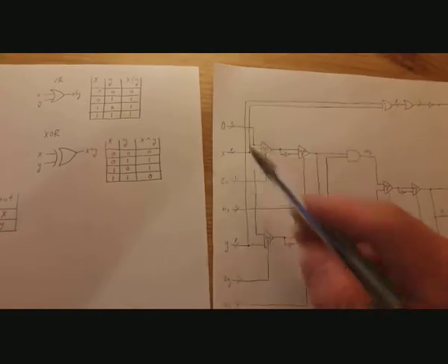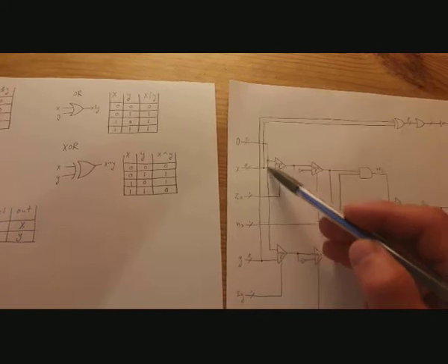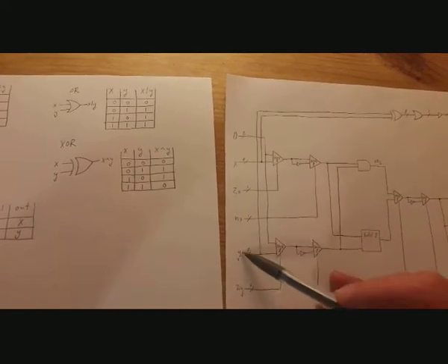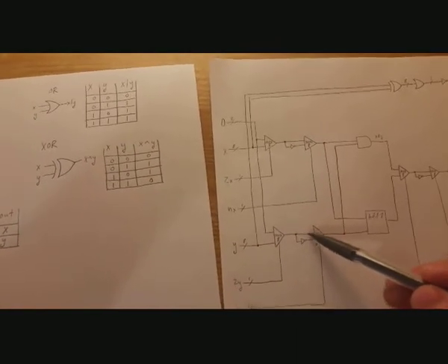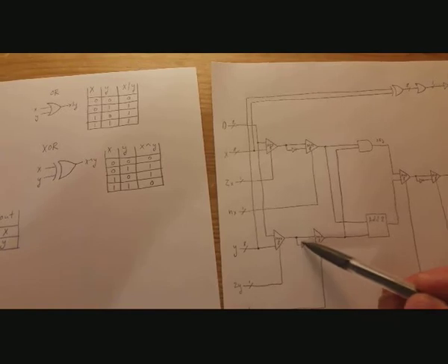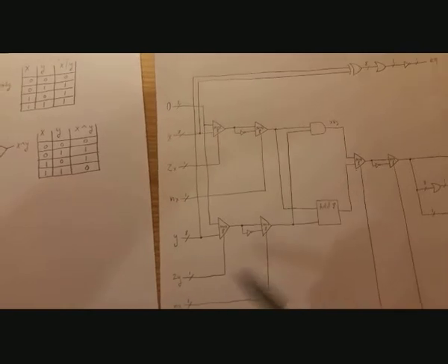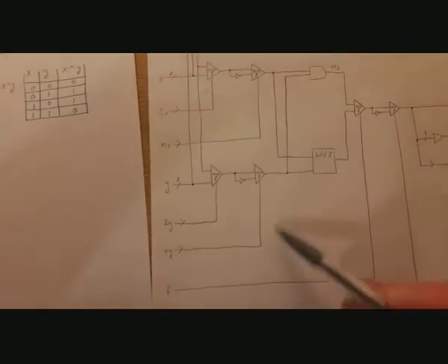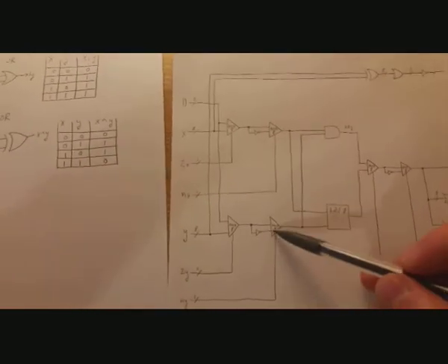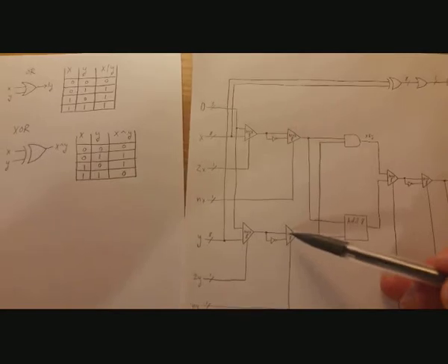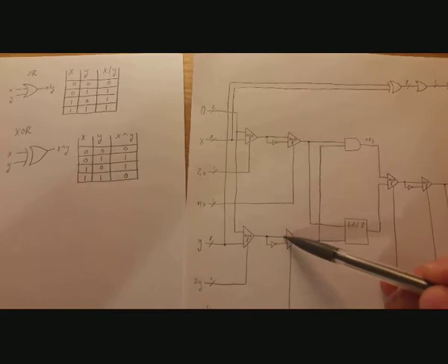Same logic there. We take in 0 here. So here's 0. It's also coming down to this multiplexer, and Y. The ZY bit controls which one we choose. It goes forward. We split it and flip the bits of one side of it and put that into another multiplexer. And this NY bit says which of those we choose to move on. So these are almost like if statements. If this is true, choose this one. If it's false, choose that one.